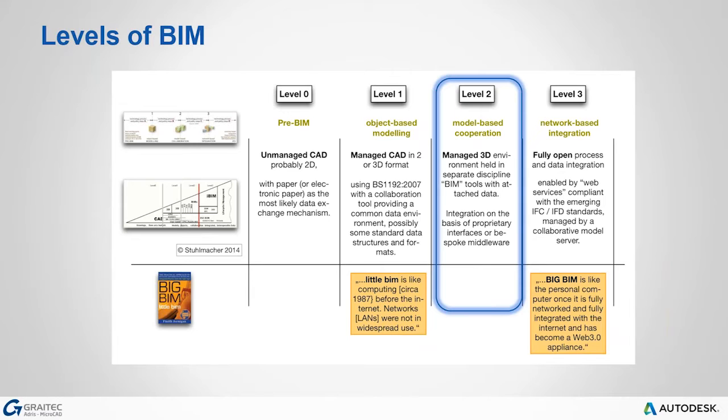Design information is shared through a common file format, which will enable any organization to combine that data in their own order to make what we now call a federated BIM model, and then to carry out interrogative checks on it. Hence, any CAD software that each party used must be capable of exporting to one common file format that all collaborators on a project can read. One popular one that's gaining a lot of ground is IFC. IFC stands for Industry Foundation Class.